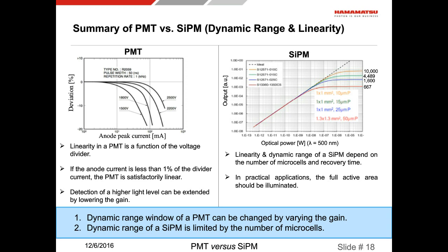In practical applications, it is highly advised that a SiPM is uniformly illuminated. If one spot illuminates a certain portion of the SiPM, the dynamic range is going to go down. This is not so for PMTs.